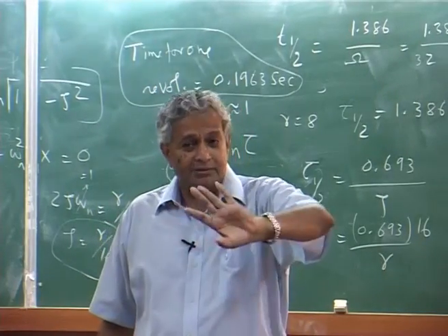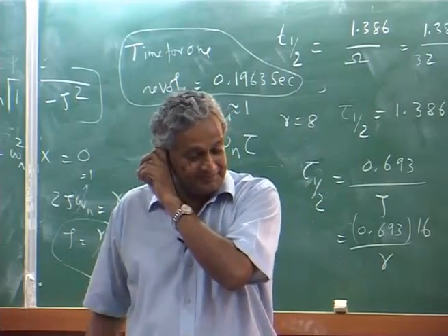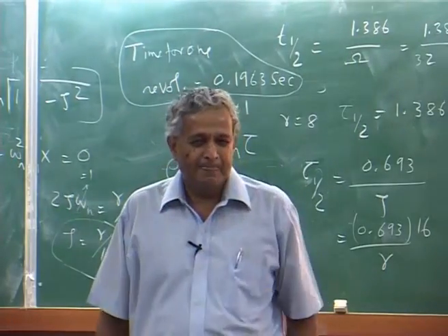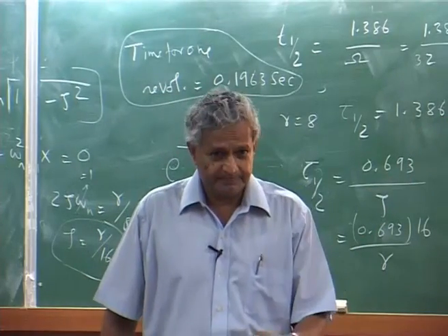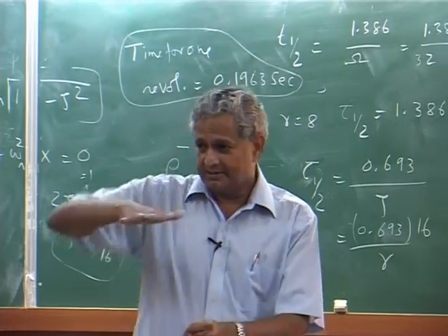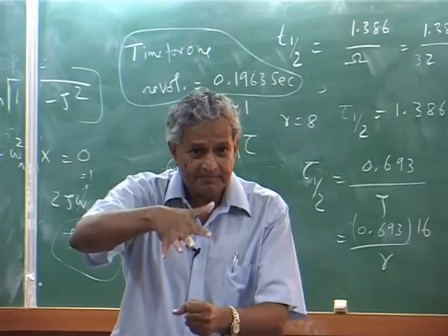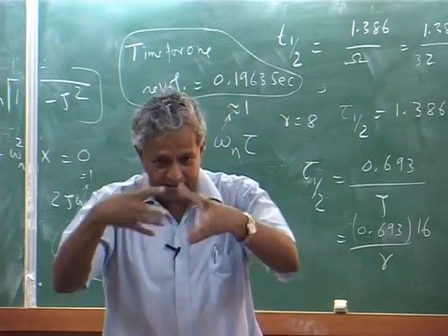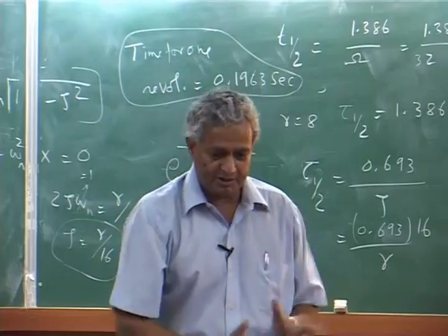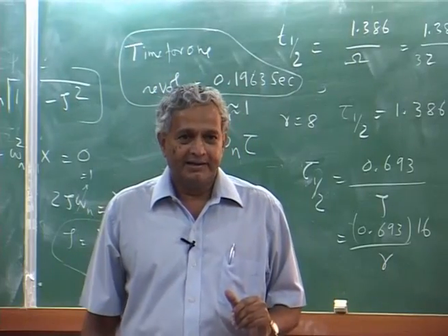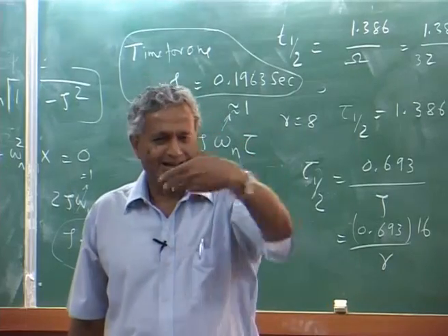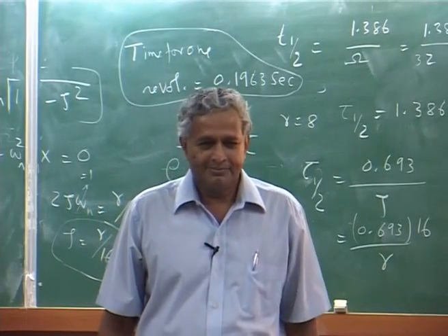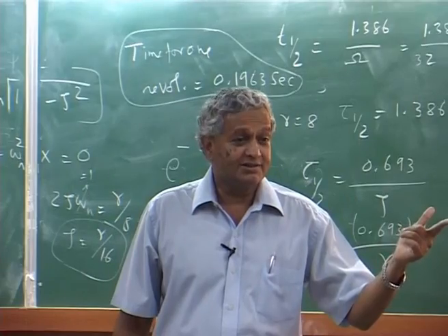Now I am coming to our flight dynamics. The pilot gives an input to the rotor blade, the blade immediately flaps, then it gives the hub moments and the helicopter responds. The delay between pilot input and the response of the blade, I am neglecting it. I say that it responds instantaneously.